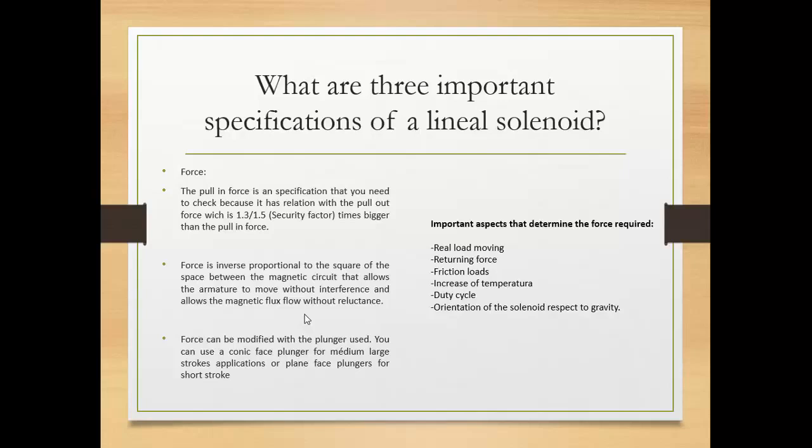Force can be modified with the plunger you use. You can use a conic plunger for medium to large stroke applications, or a plain face plunger, which applies for shorter strokes.